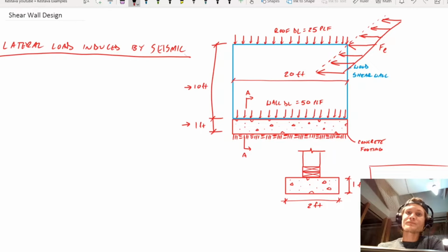So today we are going to get back to shear wall design. That was a really highly recommended one that a lot of you wanted to know more about. So we're doing wood construction again, and we are going to finish wrapping up how to design a shear wall. Before, we checked the global stability of our shear wall, and now we're really going to get down into the nitty-gritty of how you size the thickness of sheathing that goes on there, the structural panels, what type of grade, and where you get that information.